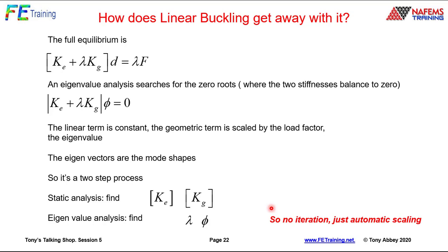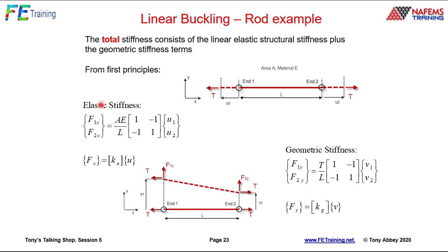But does it give the right answer or not? Again, it is another good question. If our assumptions for this stiffness matrix, which are linear, small displacement, and those approaches, hold, then we're okay. And that's typically true for slender type structures. So here's a very quick run through.